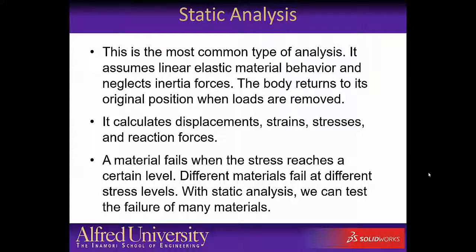In static analysis, we calculate displacements and the normalized displacements called strains. Using constitutive relationships, SOLIDWORKS can then calculate the stresses within the body correlated to those strain values, and the internal reaction forces that are represented by those stresses. A material fails when the stress value reaches a certain level. Different materials fail at different stress levels. With static analysis, we can test the failure of many materials.